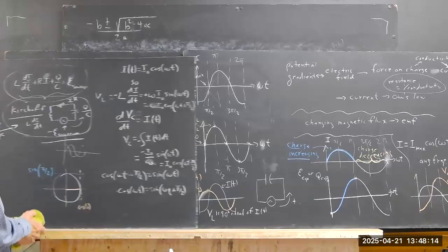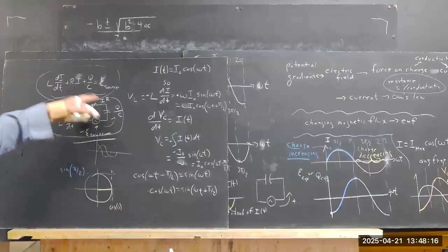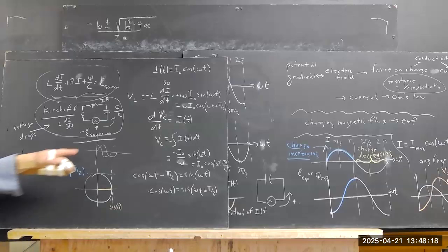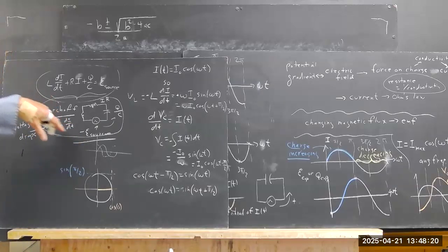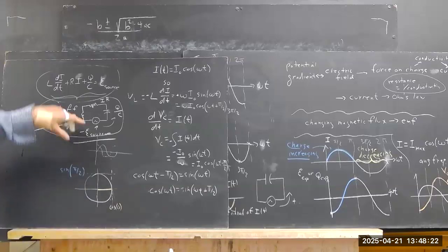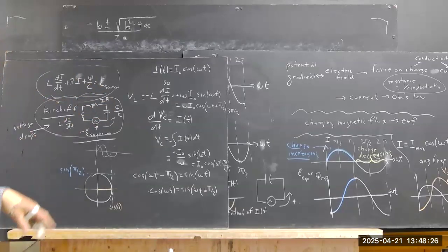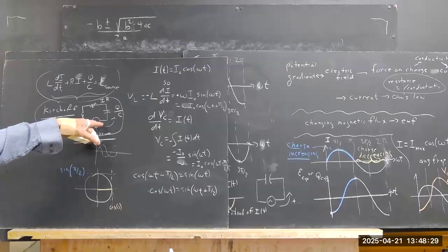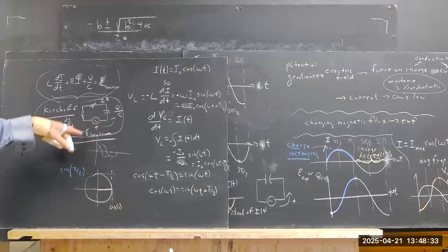Now, it really comes down to this: Kirchhoff's laws, we've been over it. We have voltage drops from one point of the circuit back to the same point. Whatever the EMF of the source is, we're going opposed to the source when we do this, so we have negative EMF of the source here.